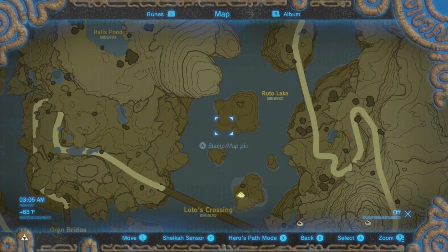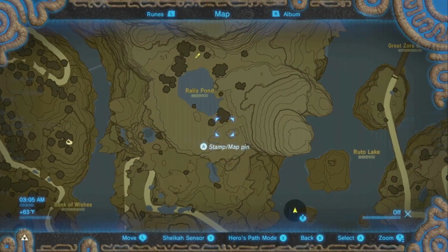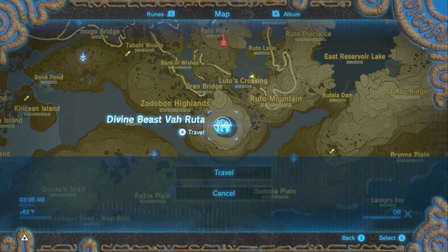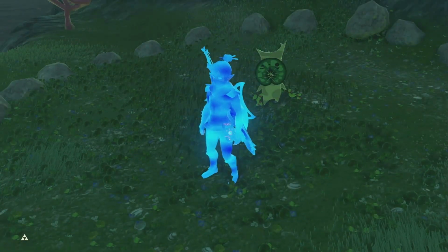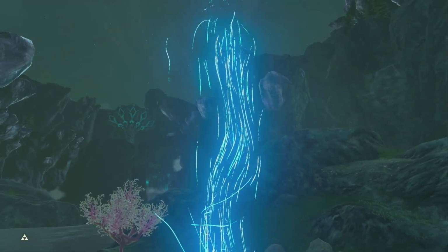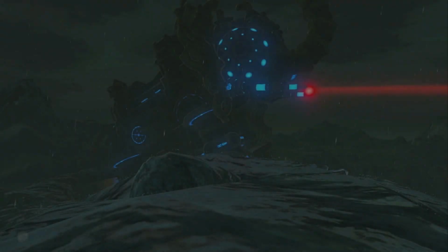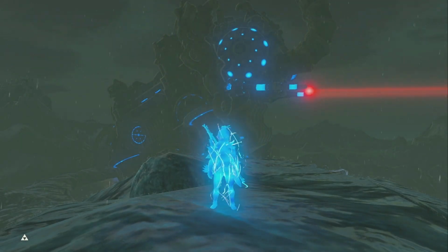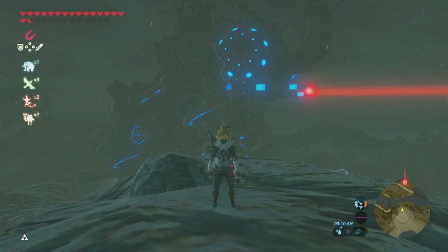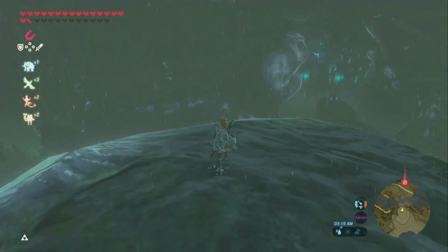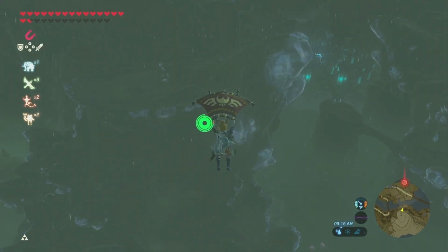A fan-assisted water heater draws in large amounts of room air to dilute the exhaust products. Dilute with tons of house air. If you mix 70 degrees Fahrenheit or 21 degrees Celsius room air with 400 degrees Fahrenheit or 204 degrees Celsius exhaust products, you can cool the exhaust products.